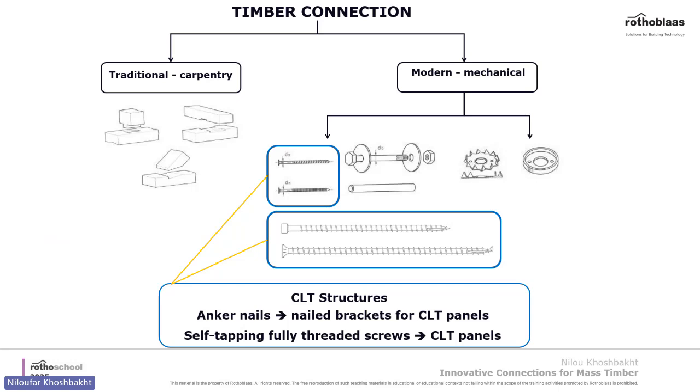And also the other thing is when you create the tenon or any cut you put in the timber, you reduce the cross section of the beam. So for example, if you start with a 8x8 beam, the effective load-bearing capacity might be equal to a 6x6 beam. And also they require workload. Sometimes their workload increases exponentially, so you should be careful with the cost you end up with.